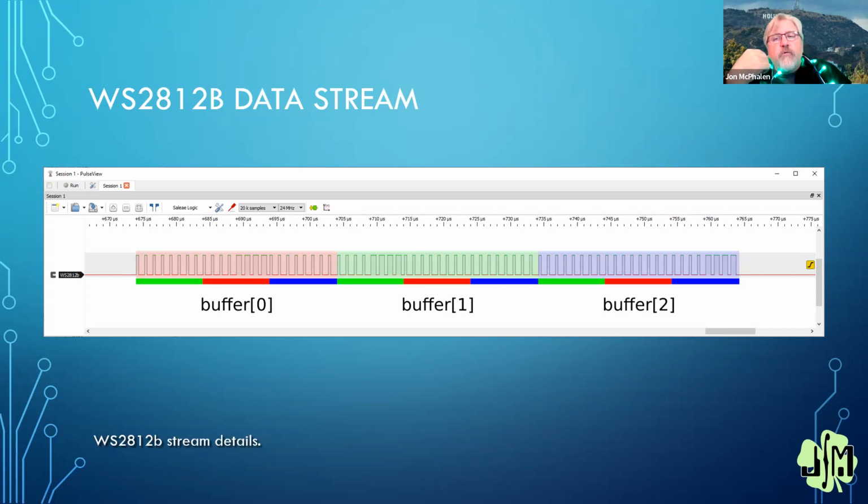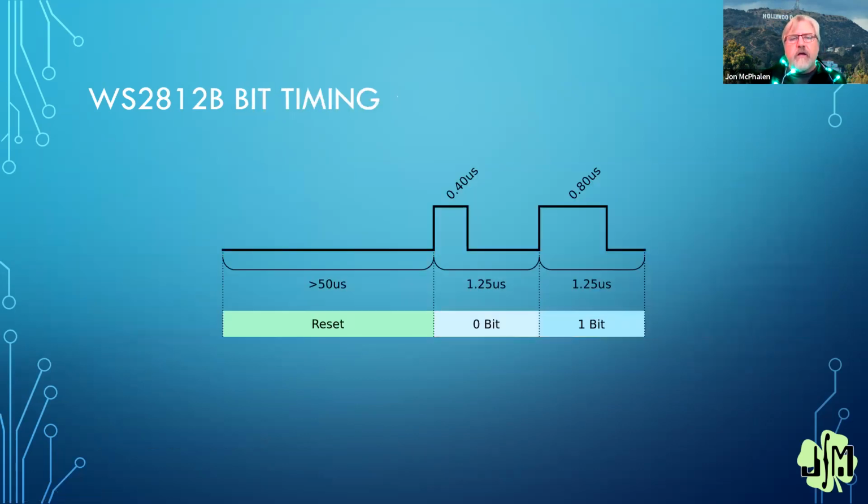So if you are running a project and you're trying to make something red and it's green or vice versa, change your driver. If it is a WS2811, if you've told it that's what it is, change it to WS2812, because that's really the difference between the two: there are some small timing variations you can see here. All of this is the same. The 0 pulse and the 1 pulse in the WS2812 are a little wider. I think that's for reliability, but you can run WS2812s with the WS2811 driver.